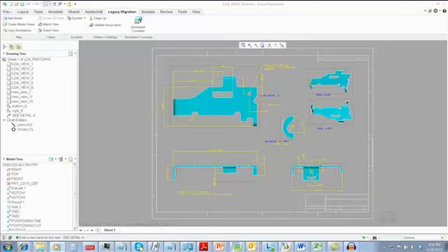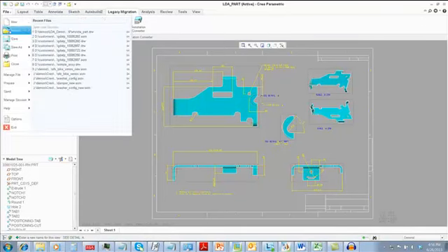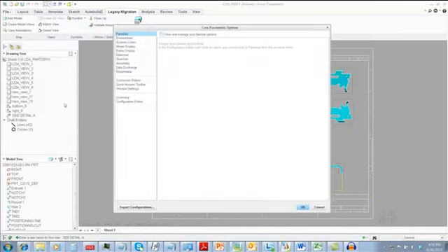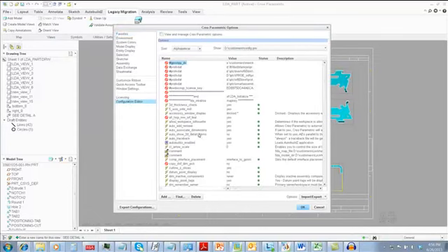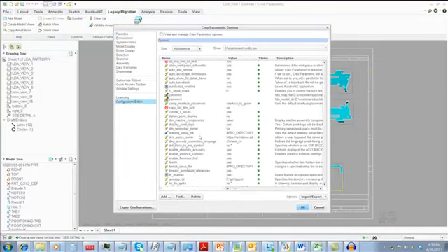Legacy Migration Extension Step 2: Reproducing Dimensions and Notes. Before using the Copy Annotations command to automatically recreate dimensions associative to the solid model views, we check that the config.pro option called Forward Annotation References exists and is set to Yes.